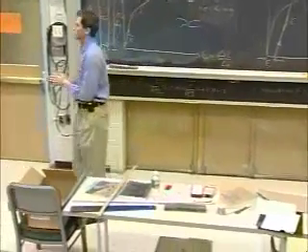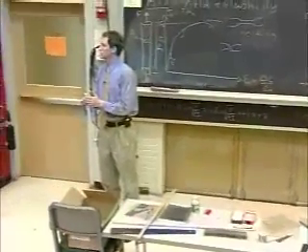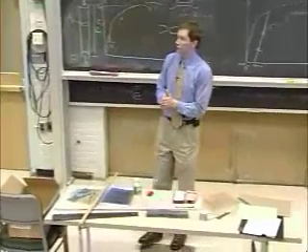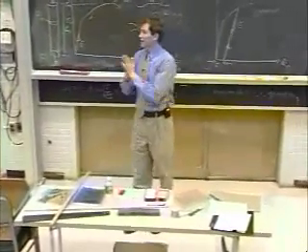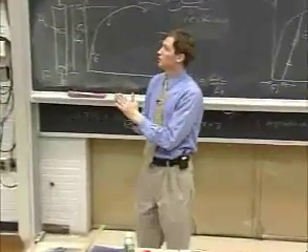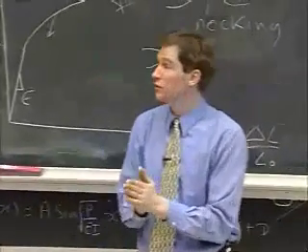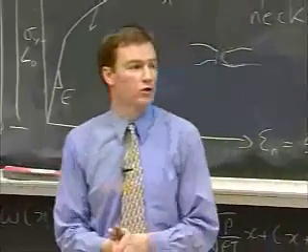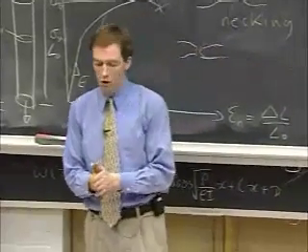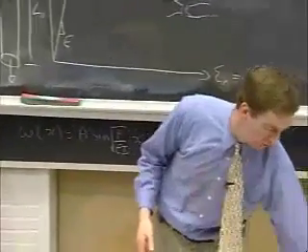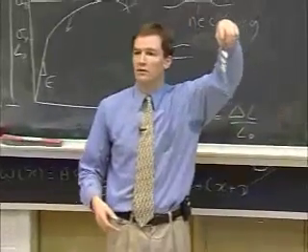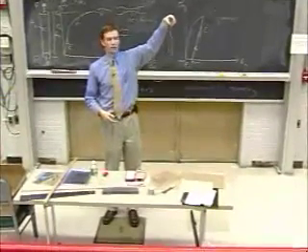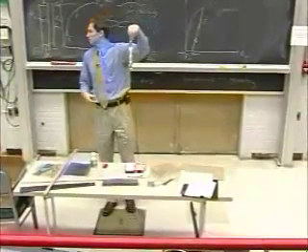Well, is it ever the case in manufacturing that someone might purposely stress something past yield and make it strong? Absolutely. And in fact, there's no metal that you're going to use as an engineer that hasn't been deliberately work hardened in order to get a certain yield stress. What are examples of this? What might you do to work harden a piece of steel, or even this foil has been work hardened? How do you make foil? Anyone? Just basically roll it into sheets.